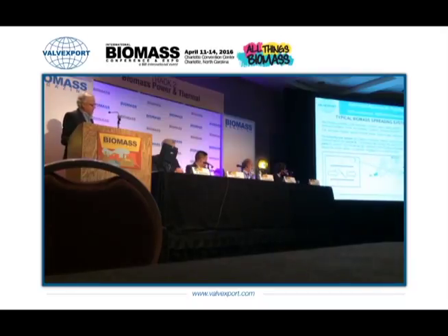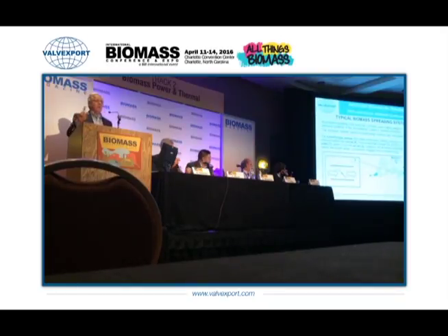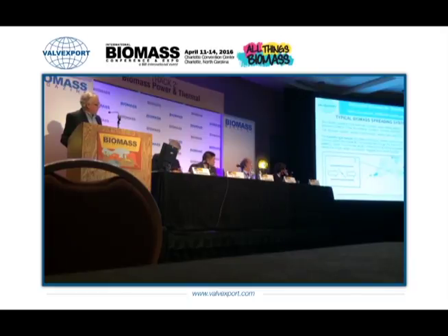The typical biomass spreading system is this system. It uses a butterfly valve that is rotating continuously. They can usually change the frequency or the RPM, and it discharges into a nozzle, and that nozzle basically creates, as we will see in a minute, a continuous back and forth cycle that really does not provide any predefined control, and it cannot be changed. Once you have the butterfly turning, you get what we're going to see in a second.